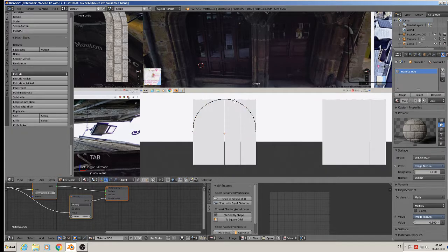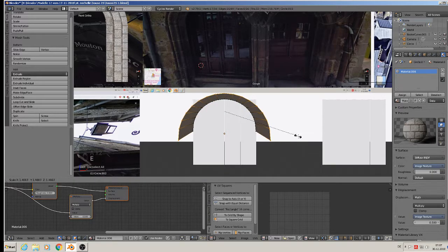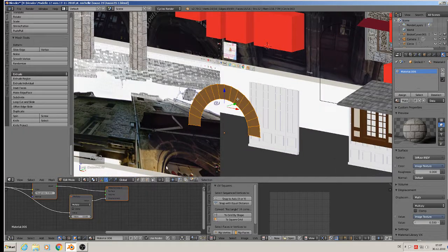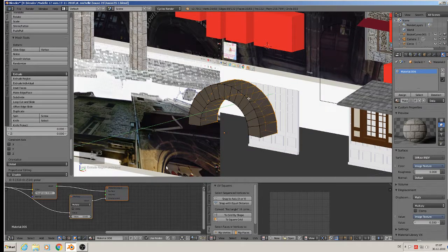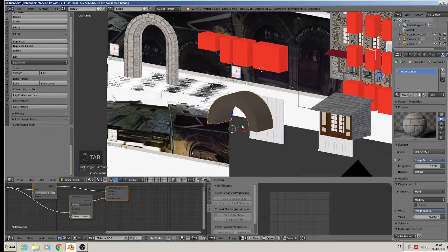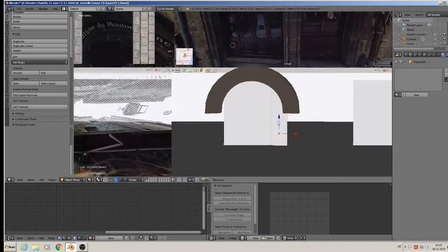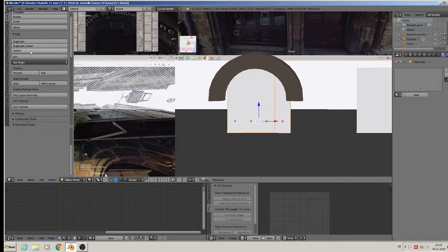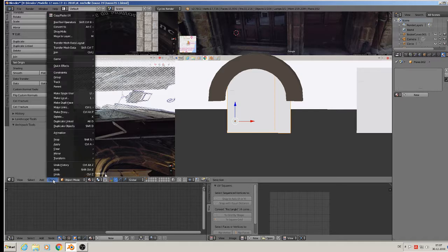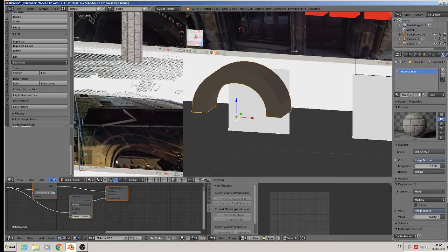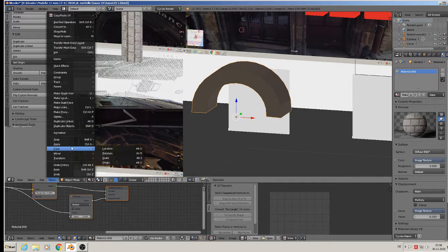So then we take here all with A and extrude scale. So we have that. Bring that a little up and take all and extrude that backward. So we have the cutting object now. That means we have to join all 4 of these together. Then object, apply rotation scale of the object. The same you must do with the cutting object. So object, apply rotation scale.